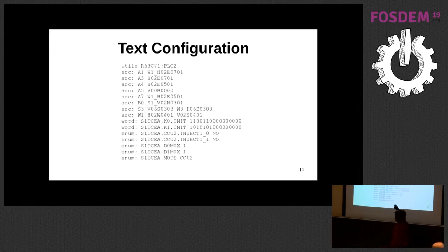You have it split up into tiles. You have the arcs, the connections, configuration words like LUT initialization, and the enums, which are like textual settings. So this is a slice configured in carry mode.